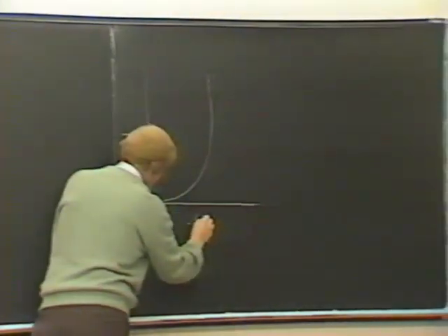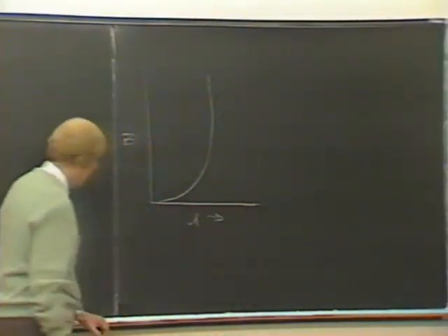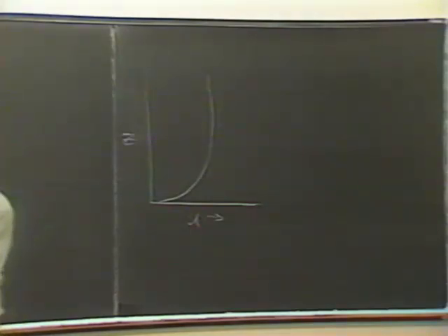But near the bed, right at a smooth bed surface where the roughness isn't too great, the flow must be laminar, or at least at times be laminar. And the thickness of that laminar or viscous layer will grow until it becomes unstable, and then it collapses, wiped out. Then it grows again until it becomes unstable and collapses.